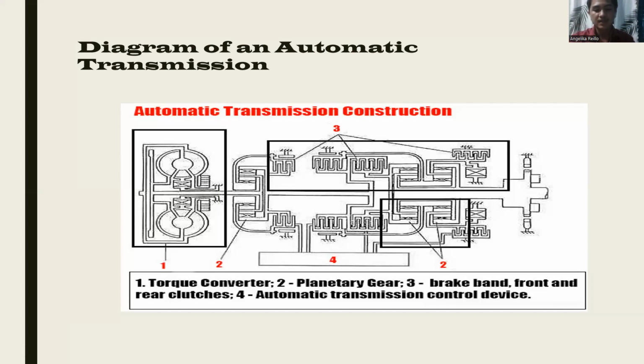The torque converter is subjected to high loads during operation, so that each part does not wear out, it is filled with transmission fluid. Rotary gear. Automatic transmissions use rotary gears. In the automatic transmission case, there are several rotary mechanisms that provide the required gear ratio. The transfer of torque from the engine to the wheels occurs with the help of friction discs through rotary gears, differential, and other devices. The devices are controlled by the control and monitoring system through the use of transmission fluid.